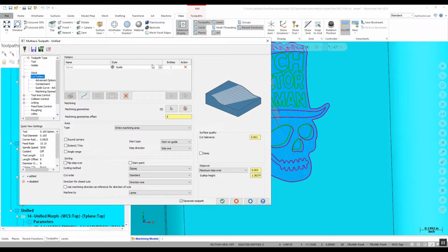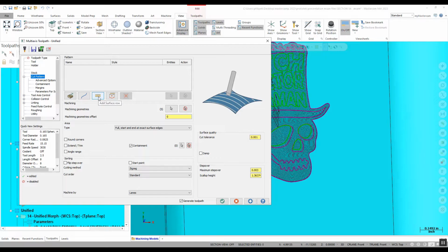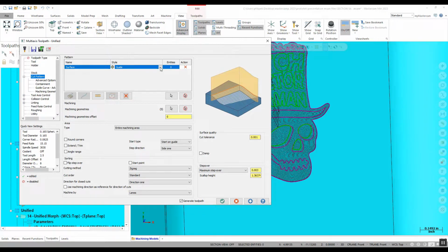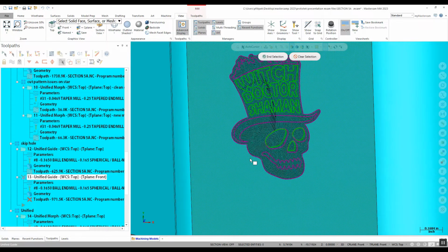Other options in here would be surface sets. If I go to surface, now I'm guiding about a parallel guide or flow lines now. So flow lines are going to flow against the U and V. Where these come in, it's potentially like a pinion shaft and stuff like that, where you have nice flow lines along them features. Otherwise, if I guide this, now I can go and I can pick surfaces.